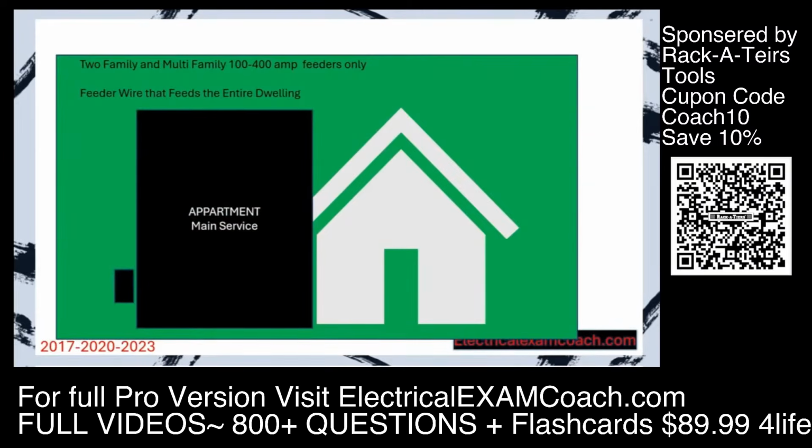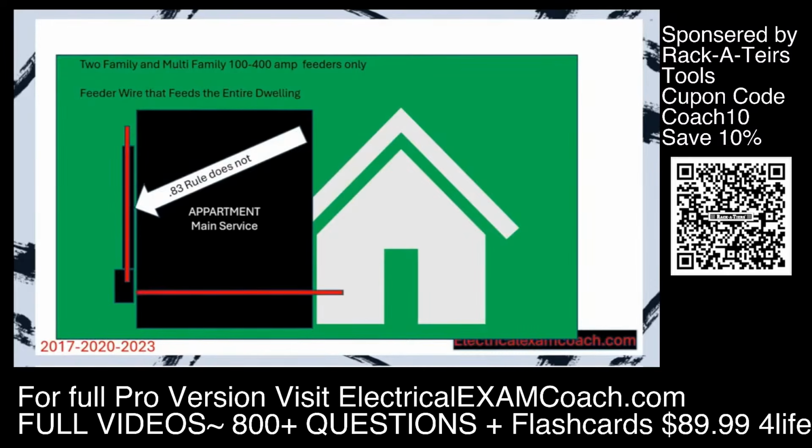Let's imagine that you have your meter center out here, you have your service riser, and then you have your wire going up. That wire there, the 83% rule does not apply. You're going to use all of the previous rules that we learned before and apply those. But the individual feeder going into that unit does.